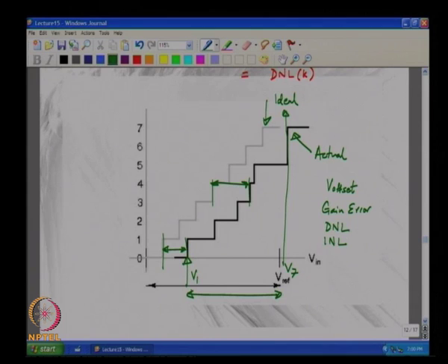An even better way of doing this is to calculate my LSB after removing the so-called gain error. Gain error is nothing but LSB size not being what you wanted it to be. Removing gain error means I make what I wanted equal to what it actually is, but unfortunately the step sizes are not uniform, so you need some kind of average step size.